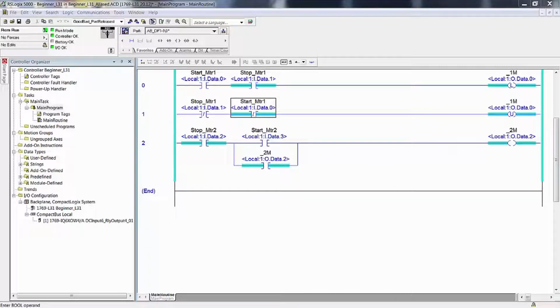And once again, we demonstrated what I pointed out in an earlier video, even though we weren't this far in the lab book yet. I had you go to the program mode and then watch 2M, watch the last rung, and then go back to the run mode. See, you lost the on state of 2M but not of 1M. And that's because on the very first program scan, OTEs are treated differently than OTLs and OTUs.